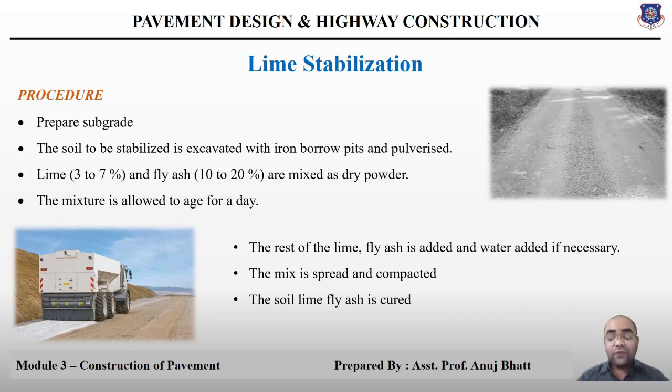After that you have to make the field checks. Field tests are to be conducted to check first the moisture content during the compaction and the dry density after the compaction. After conducting the tests and checking the results, you may allow the road or surface for traffic. So this is all about the lime stabilization.